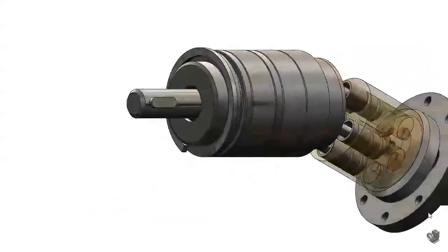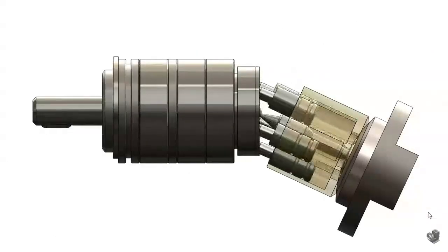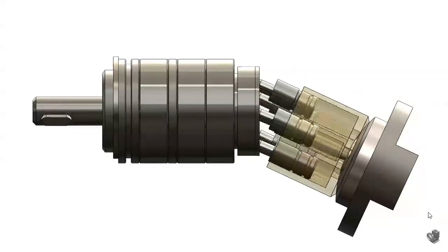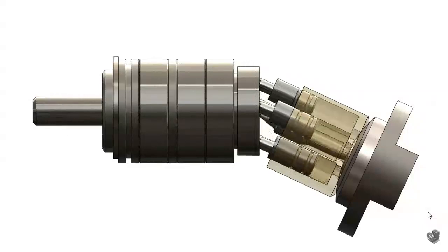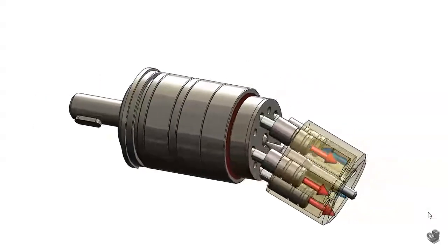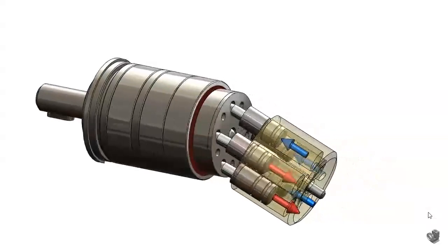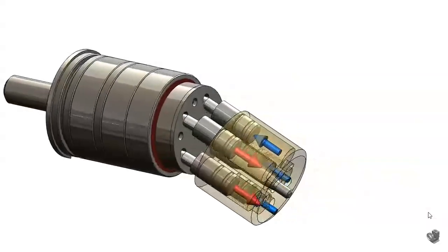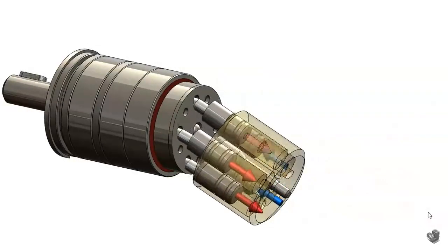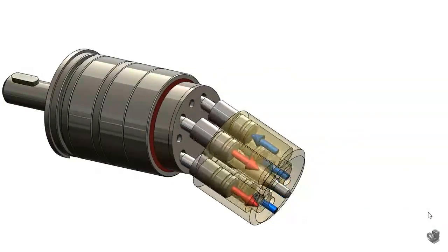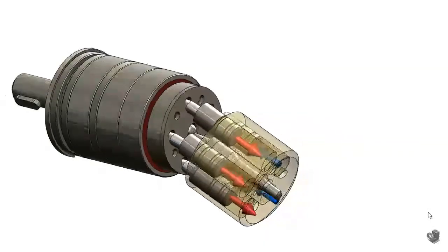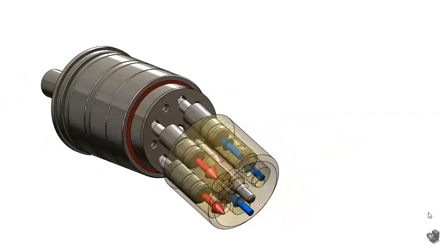The bent axis mechanism is a pumping machine, the displacement pistons of which are arranged at an angle to the drive shaft axis. As the drive shaft rotates, the cylinder block is caused to rotate by the pistons. The pistons move up and down within the cylinder block bores, converting the linear motion into rotary motion. The length of stroke is dependent on the angle of the bent axis. Fluid is fed to the low pressure port, then, as the pistons move, delivered into the high pressure port.